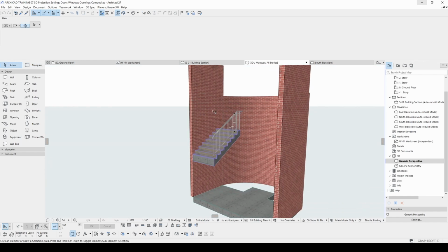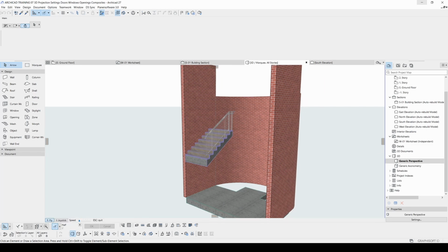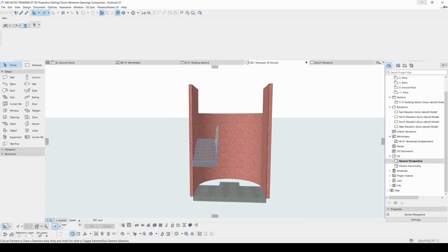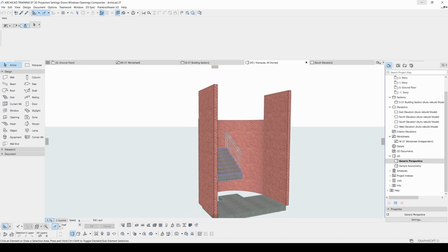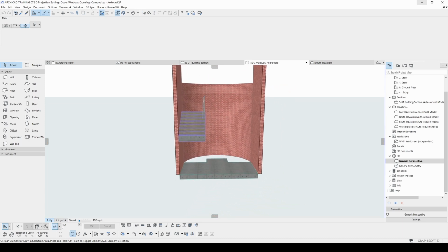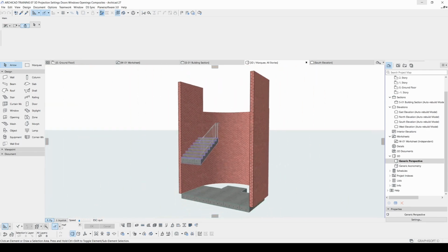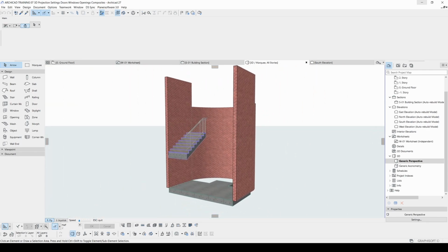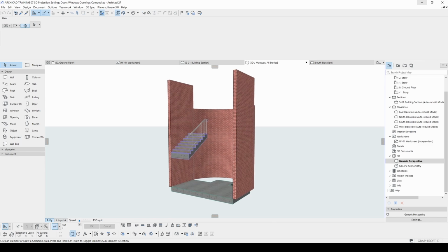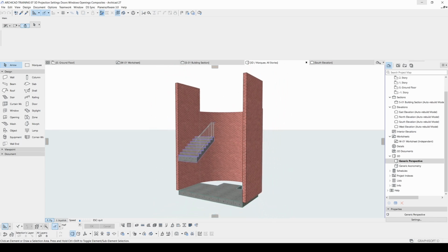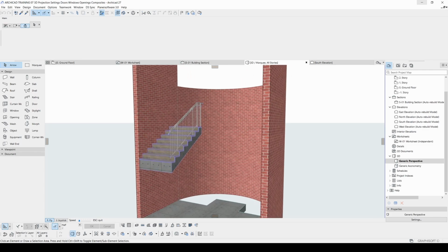Also in the 3D window, you will see this little man, which is explore icon, and you can click this. By clicking this, you can use WASD from your keyboard and you can move as third person shooter video game. If you hit shift, it will move faster, and from keyboard, if you hit plus, also it will move faster, or reverse, if you hit minus, it will move slowly.